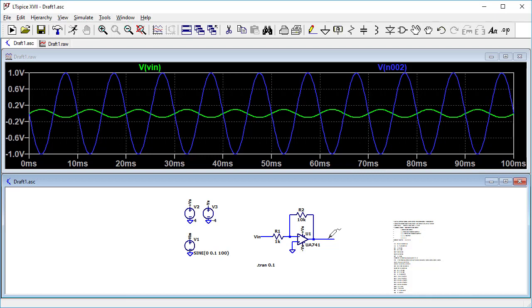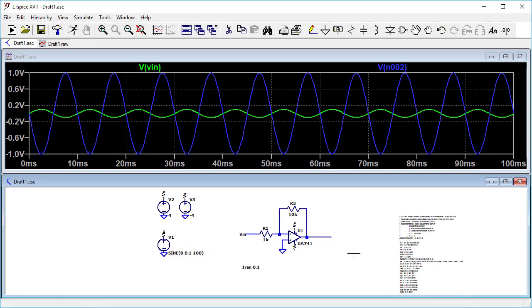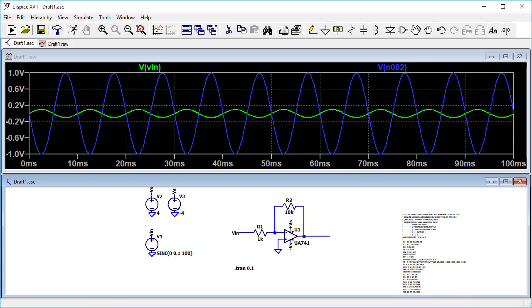This is particularly helpful if you have multiple op amps on your diagram. Rather than having to draw a bunch of wires linking up all the supplies, you can separate the supply visually from the main part of the circuit, so as not to make it overly complex visually. Hope that helps, and enjoy.